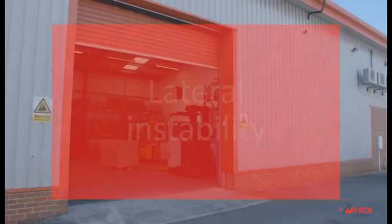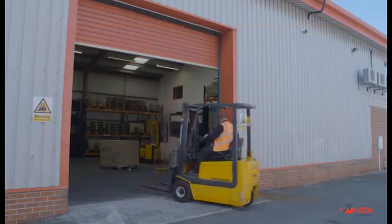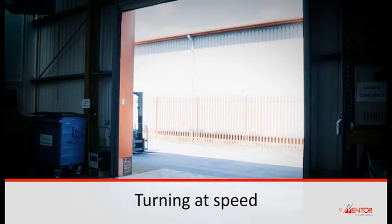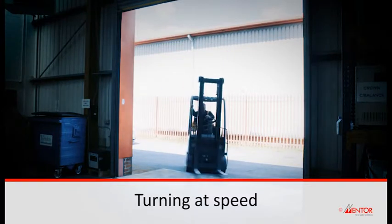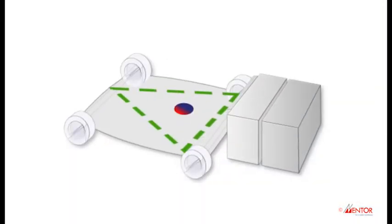We're now going to look at lateral, or side-to-side, instability. The main causes of lateral instability are turning at speed. It's important to remember that an unladen truck is less stable than a laden truck. If you remember the stability triangle, the centre of gravity is central when a truck is laden correctly.